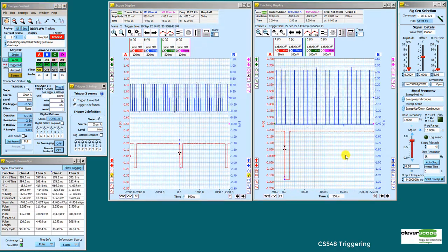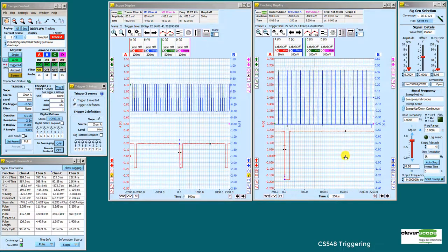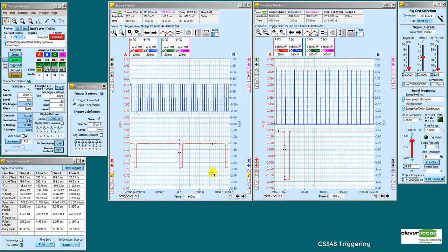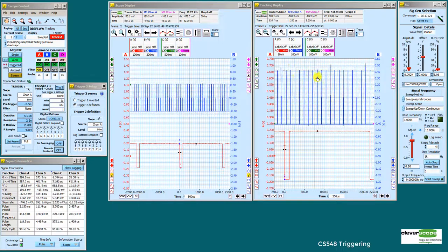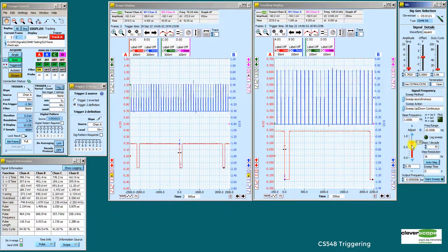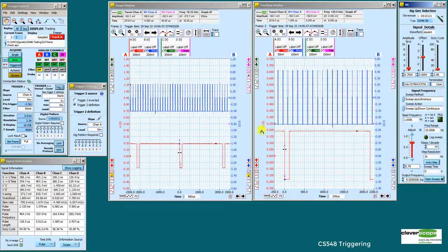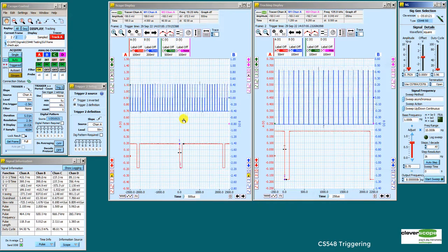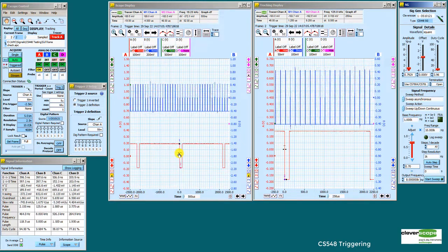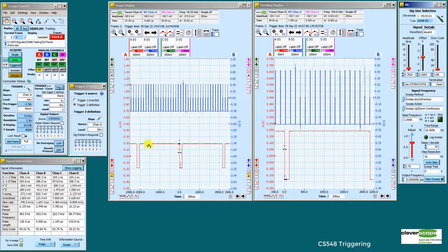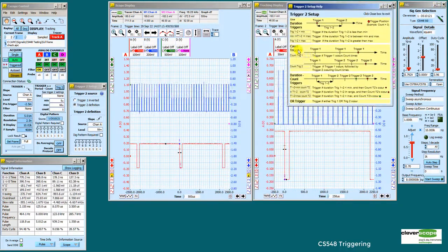Now we're going to look at some of the other triggering, the counting triggers. I've actually moved the two channels so that now channel A is the one that we can change like this, and channel B is the SIGGEN here, and my plan is to do some triggering on counts. So channel A, let's trigger on the falling edge as we are doing right now, but if we go and look at this again, we have this other option which is to count triggers.